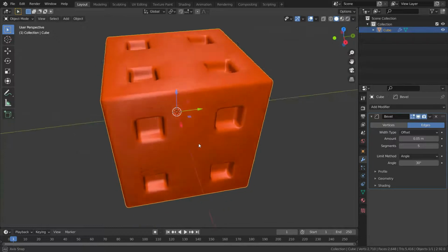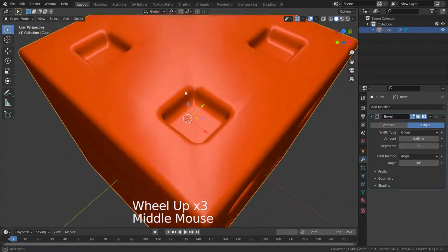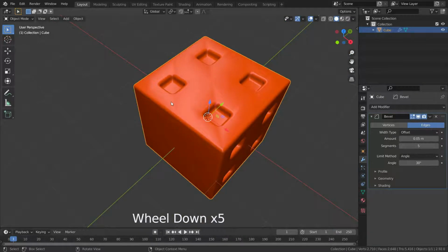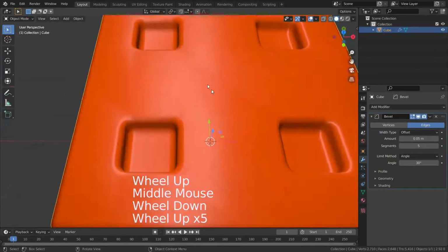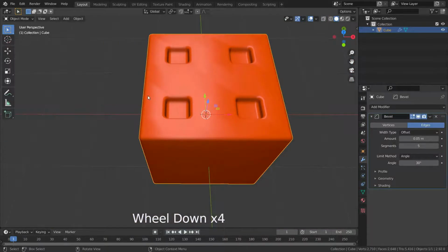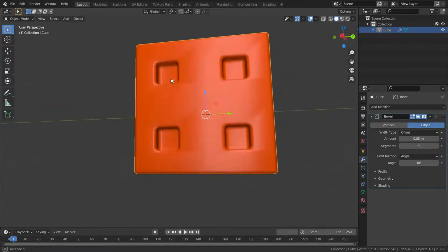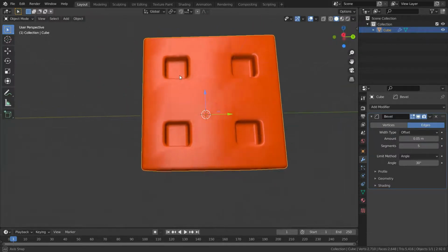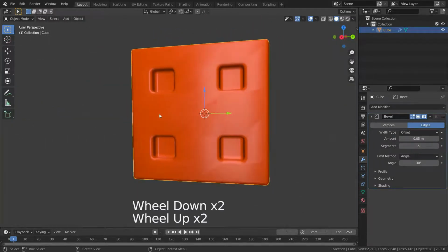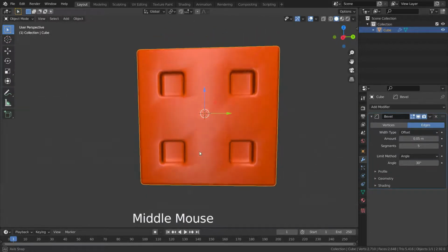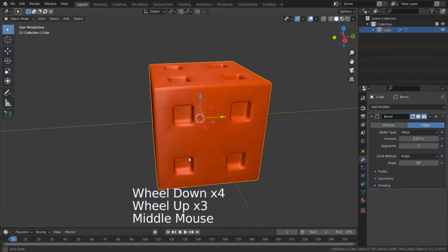Now, you have noticed that we have some weird lines extending from corners. This is happening because the smooth shading from the beveled corners is extending into the flat areas, creating gradients and lines like that. To fix this problem, we are going to open Shading option and enable the Harden Normals. But firstly we need to enable Auto Smooth option.